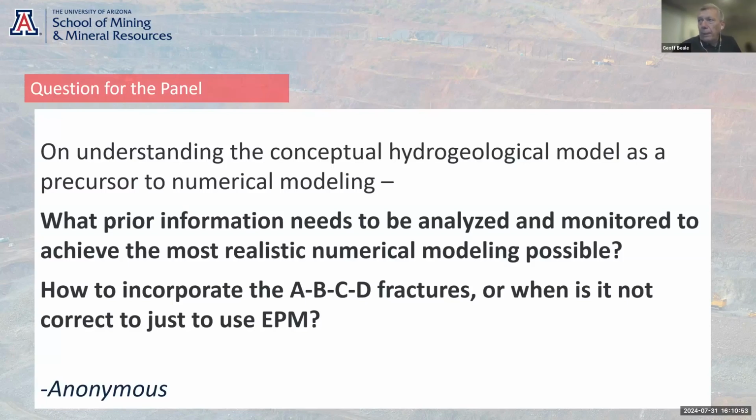The case I'm thinking about is a special case we're working on at the moment, where we've got a groundwater temperature of over 100 degrees, and we're using FEFLOW to look at the thermal transport of water through the rock mass, to see how quickly the waters will mix and cool. It's a fracture flow situation that we're applying a porous medium model to.